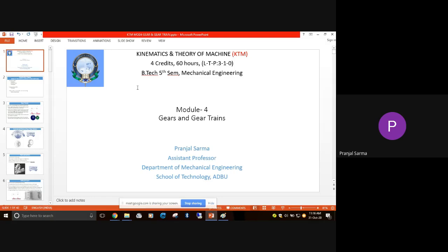From there we can very easily obtain whether the bigger gear or the smaller one is going to rotate faster. That indication helps us select, if we want to increase the velocity ratio or the speed from the driver to the driven. Suppose 500 rpm is available in the driver and you want 1000 rpm in the driven. In terms of size, we have to decide whether the meshing gear should be bigger or smaller, and how many teeth it should have. We can get somewhat of an indication.